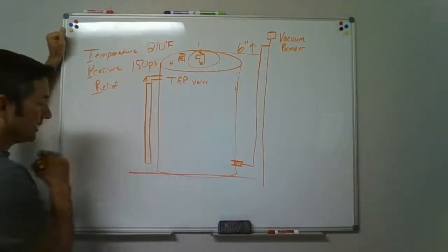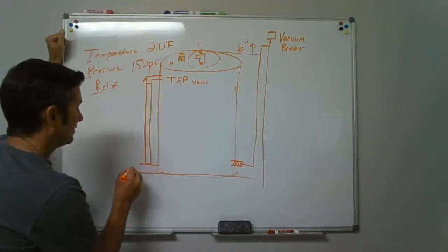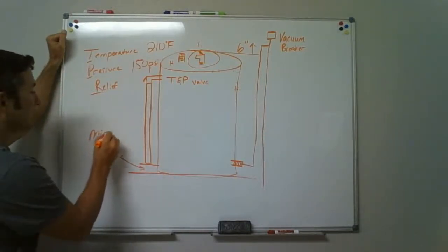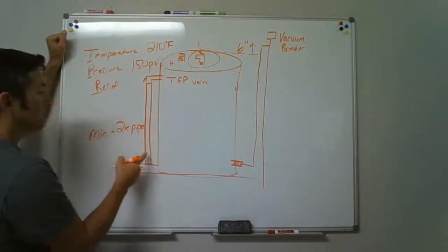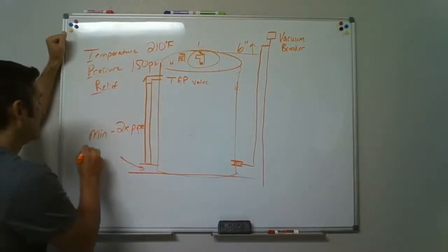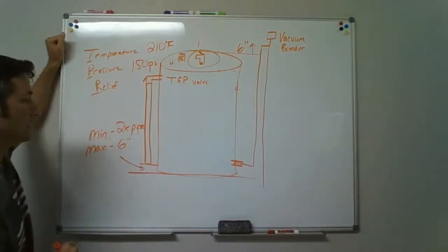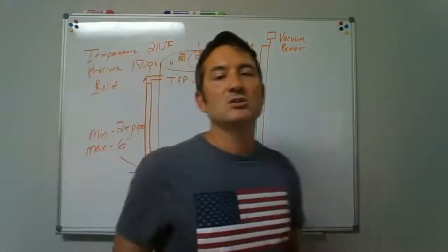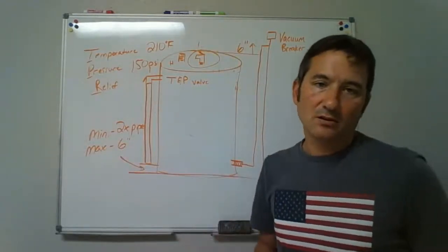Now, what we've gone over, and as you read and look at this, you'll notice that this gap down here is going to be a minimum of 2 times the pipe size, which, this was a 3/4 pipe for us that we're running, so that's going to be like 1.5 inches, and then the maximum of 6 inches. Okay. Where that gap was. Look at that stuff. Some of the things: if we were to have it up in the house, can we just discharge that down into the crawl space and say, hey, well, if it leaks, it'll just leak down to the crawl space? Is that allowable?